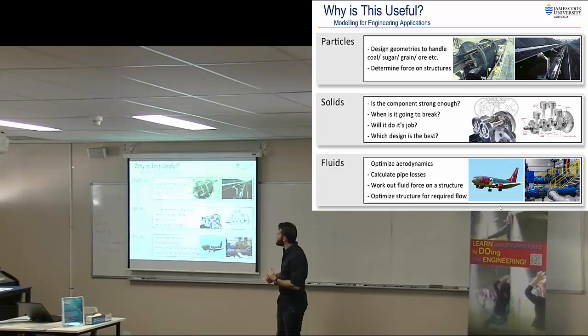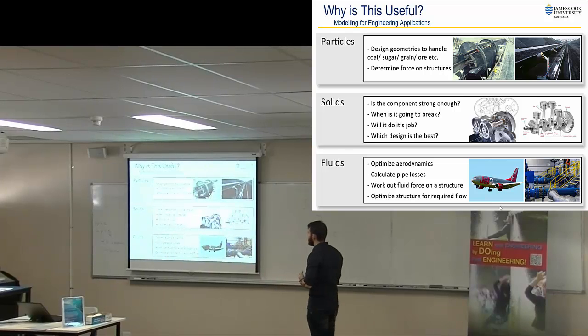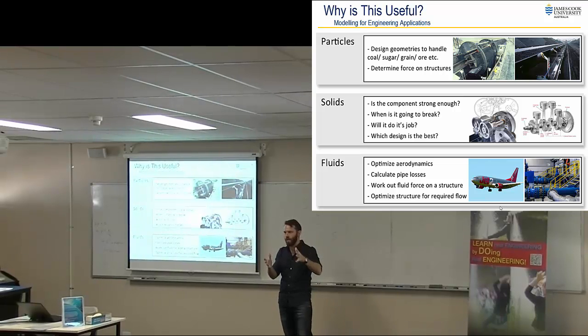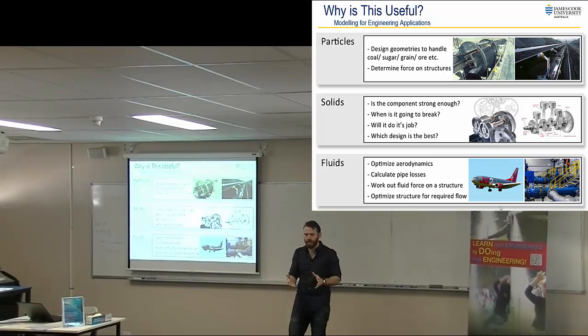This is an alternative, a tippler, where you take the entire carriage and turn the thing upside down and then back again. You'll see those in most of the sugar mills. They have that kind of technique to get the cane out of the sugar bins. And a lot of the ports have this as well. So you need to work out where the mass is going, what the mass distribution from all of those particles moving up to the edge of that carriage is. Is it going to actually wear the carriage out at the top lips of that? Is it going to break the carriage? What sort of tippler design do you need? All of that type of stuff is really critical.